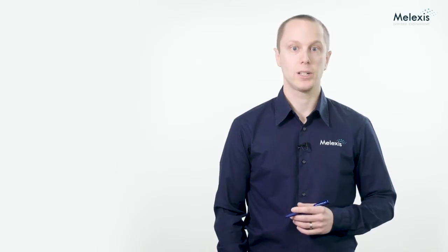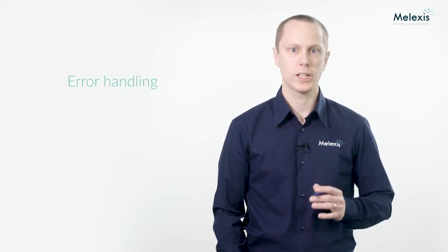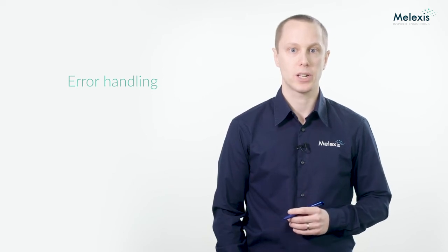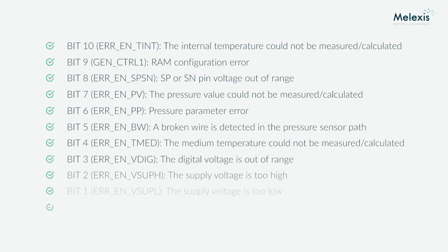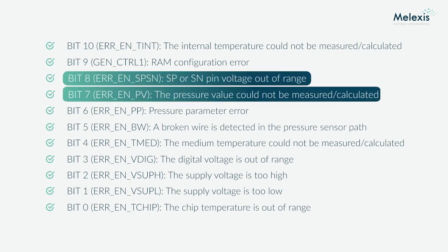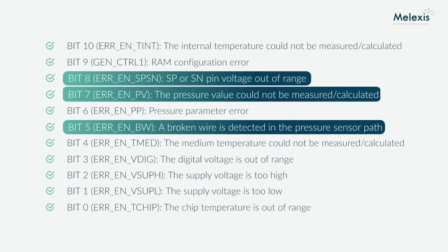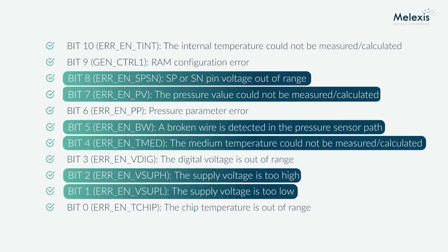The last main category in the SENT configuration is the diagnostic error reporting. Here the product offers a number of diagnostic checks which can be selected to ensure a reliable output signal to the system. These diagnostic sources cover internal influences, for example calculation overflows or ADC signals out of range, or damaged connections between the sensing element and the interface IC. They also cover external influences, like temperature or supply voltage. The supply overvoltage and undervoltage threshold levels can also be configured.